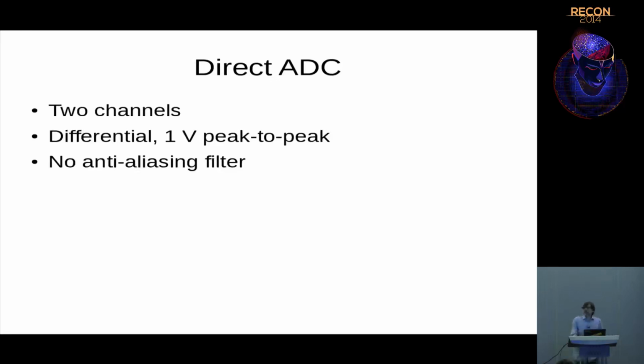And you also need to be aware that there's no anti-aliasing filter if you plug directly into the ADC. So it might be helpful to have some small circuit of your own that you plug into it. But even without doing much, just tapping in a couple of lines,